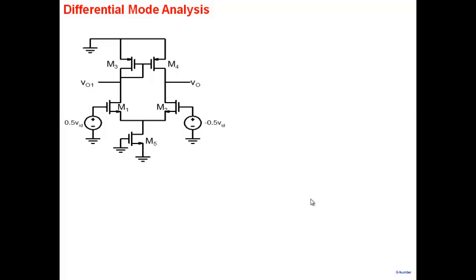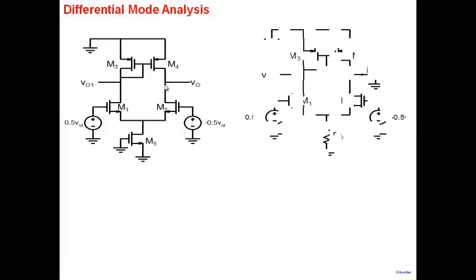We had done that for a bipolar. The way we proceed is as follows. We build a Norton's equivalent at this particular point. If the circuit is very simple, like a common source or a common gate, you can very quickly analyze. If the circuits become more complicated, the strategy that we are adopting is, at whichever node you have to calculate the gain, build a Norton's equivalent at that particular node.